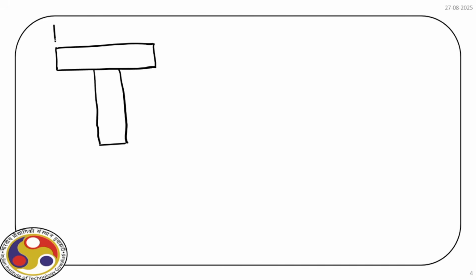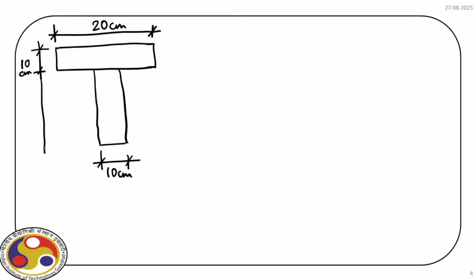Okay. Now the width at the top, say 20 centimeter. And the thickness of the flange is 10 centimeter. Thickness of the web is also 10 centimeter. And the depth of the web is again 20 centimeter.